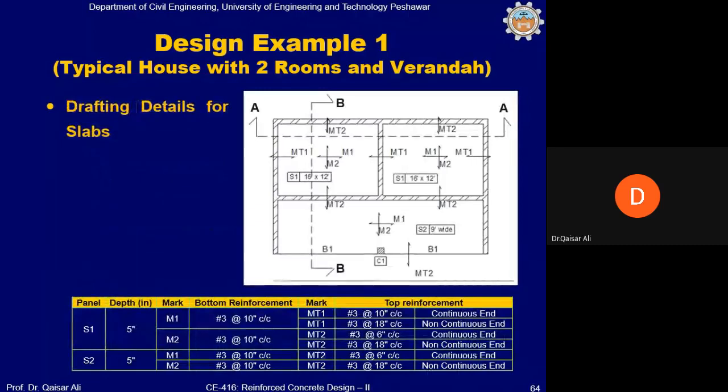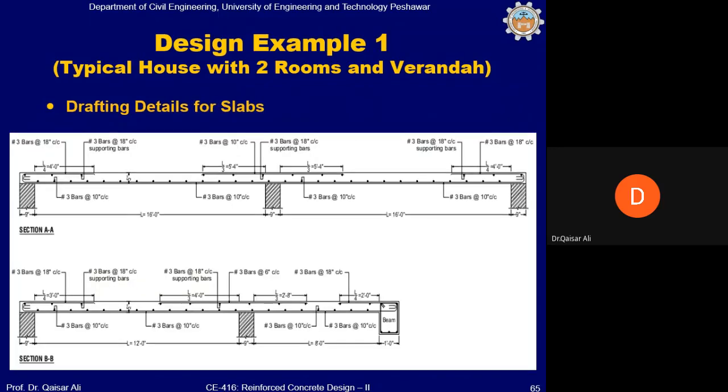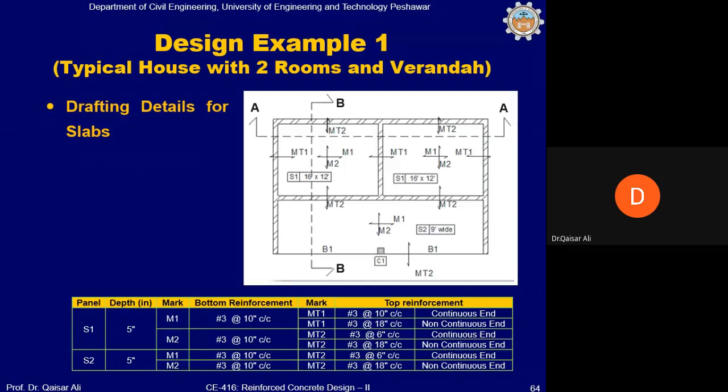यहाँ पर आप देखिए जरा. This is the table which is showing reinforcement detailing of the slab, and these are the sections. Section AA is given on this, and section BB is given along this side. Okay, along the shorter side. You will provide the main spacing closer to the bottom face along the shorter direction. ये तो आप लोगों को पता है.